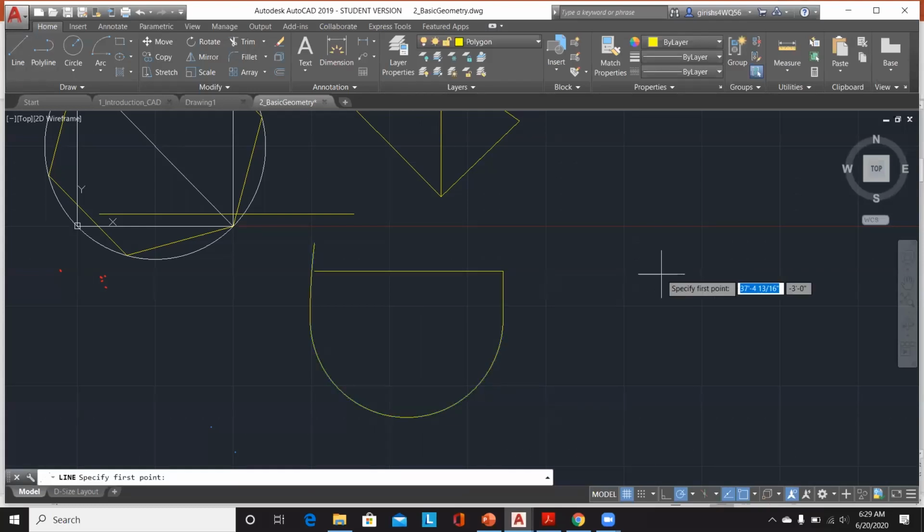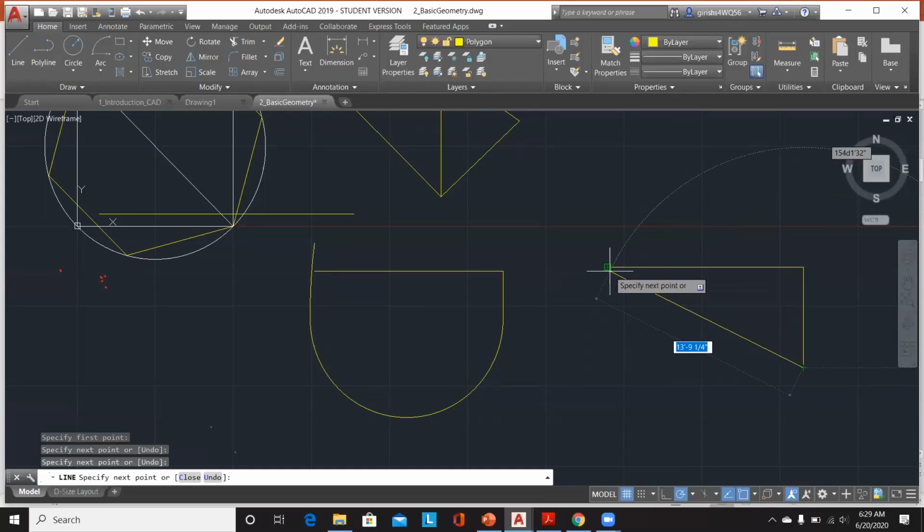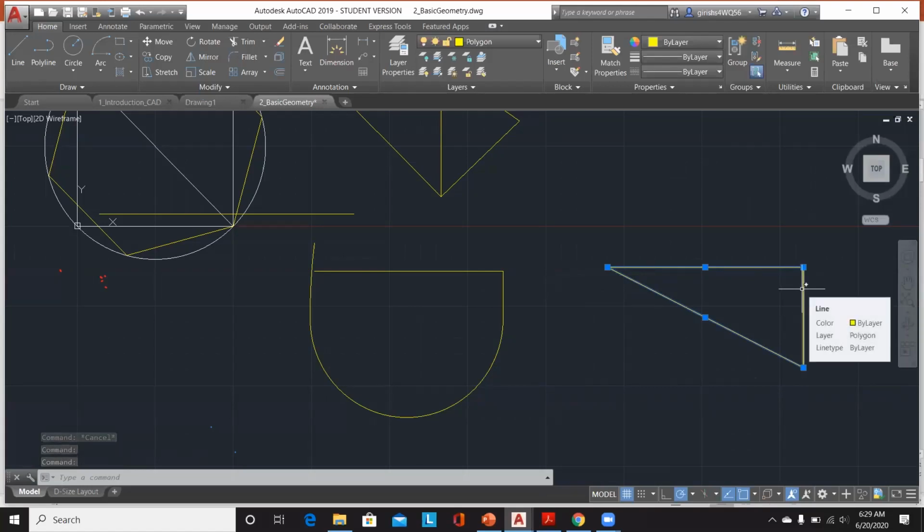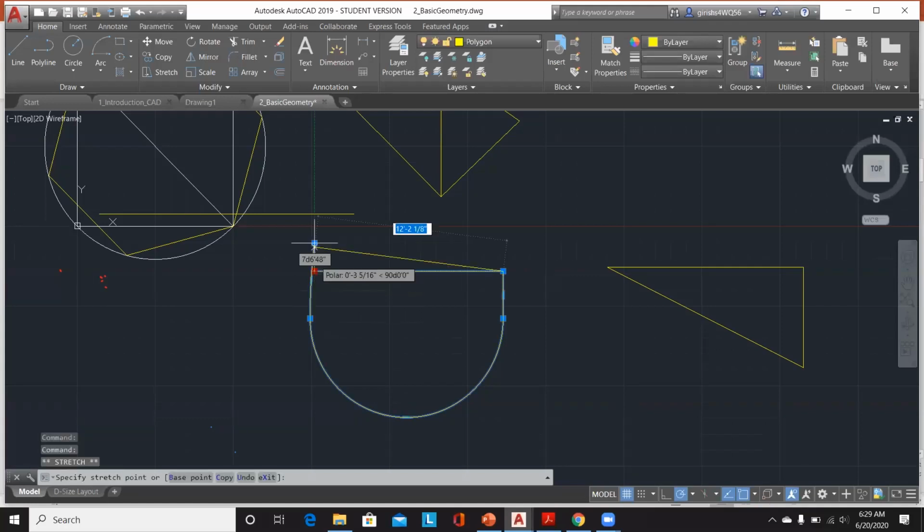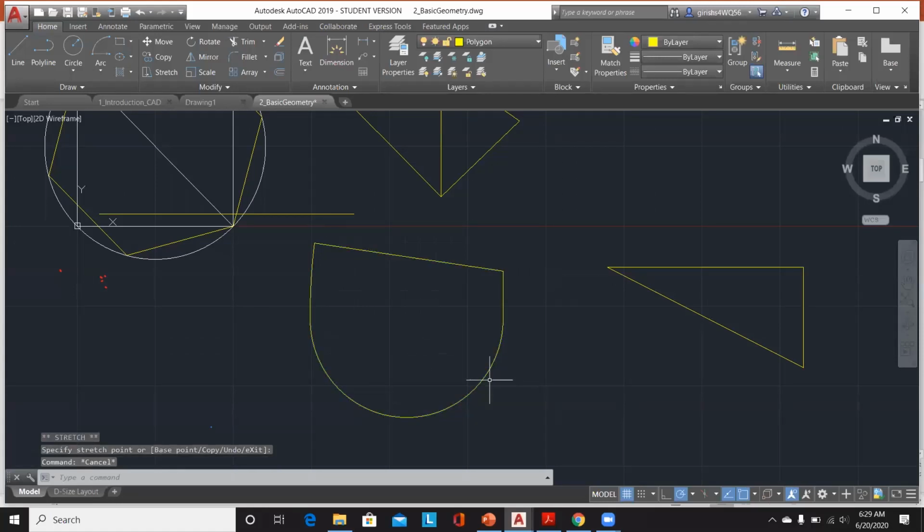For example, if you use a line to create the same drawing, I have created a series of lines using the line command, but what happens is it selects each and every line individually. So it is not integrated as of now. But when you use the polyline feature, you can create lines and arcs as a part of a line, and then integrate them, or change the angular measurements and produce new model elements that are integrated as one unit.